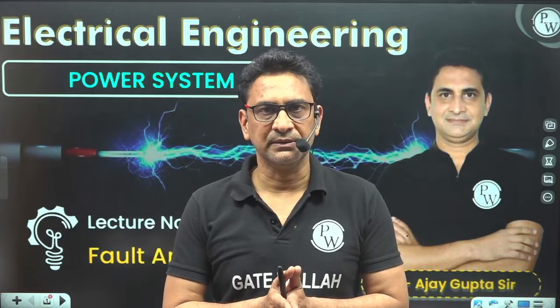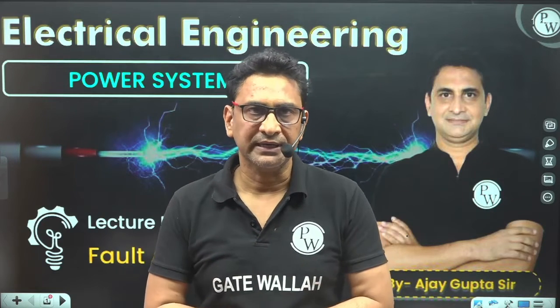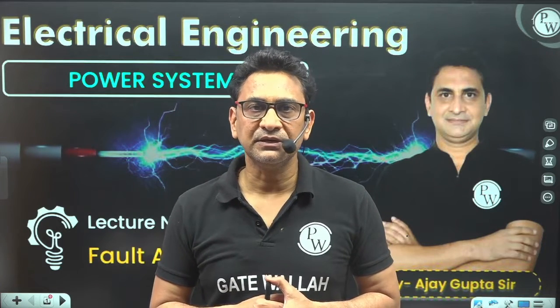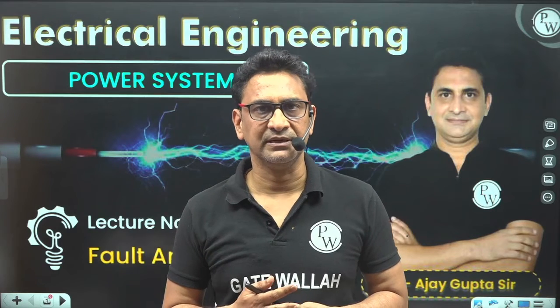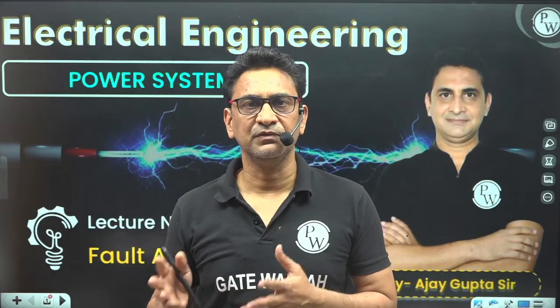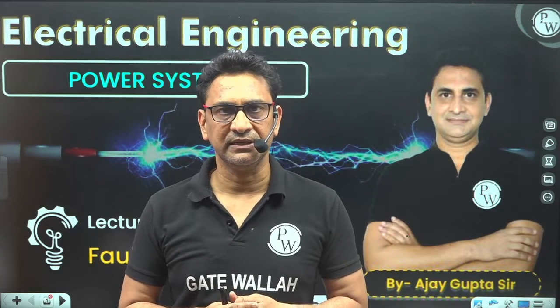So on Monday, I started the fault analysis in the power system and I told you we can classify faults into two categories. It may be the series fault and the shunt fault. We will be focusing our discussion only on the shunt fault. The shunt fault again can be classified into two categories. One is the symmetrical fault and second is the unsymmetrical fault. If all three phases are involved in the fault then it is a symmetrical fault. If only one phase or two phases are involved, then such type of fault is called the unsymmetrical fault.